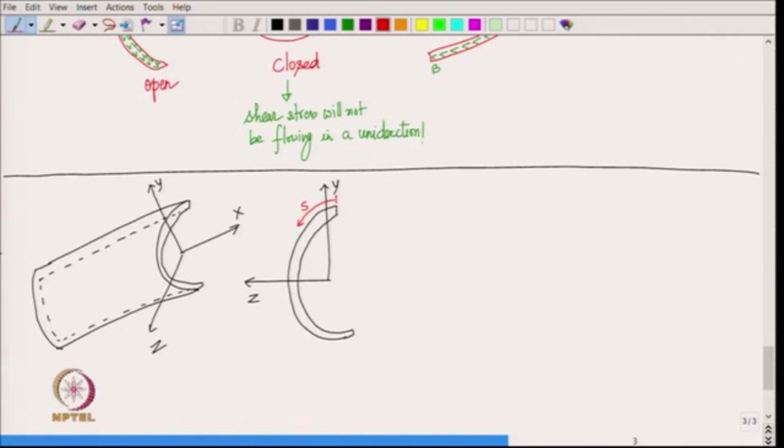So, in this case then shear stress is only going to vary as S changes for a given S. So, for a given S we have these points, and everywhere along these points we know that shear stress is in the direction along the boundary of the cross section, and then it is also uniform along that line, because there is no space for variation.